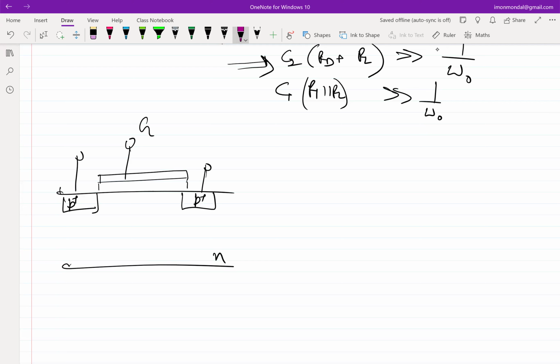If we mark this as source and this as drain, we said that if we put a battery between gate and source where the gate voltage was lower than the source voltage, there will be electric fields pointing in this direction, and mobile holes will gather here. Now if I apply some voltage between the drain and the source, there will be current flow. So this was essentially a PMOSFET device.